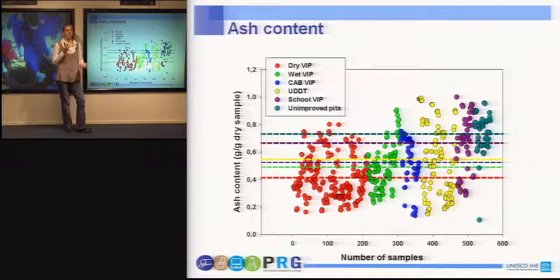Why? Because all the sludges vary significantly in their moisture content. Unlike wastewater, where the moisture content is over 98, 99%, here we have a large variation, as we saw earlier. And we would like to have a more stable basis for comparison of the data. So that's why we have been expressing it in gram per gram total solids.